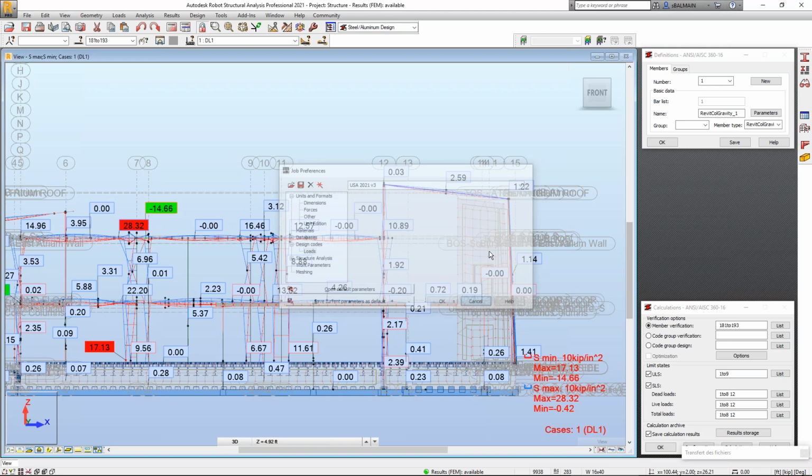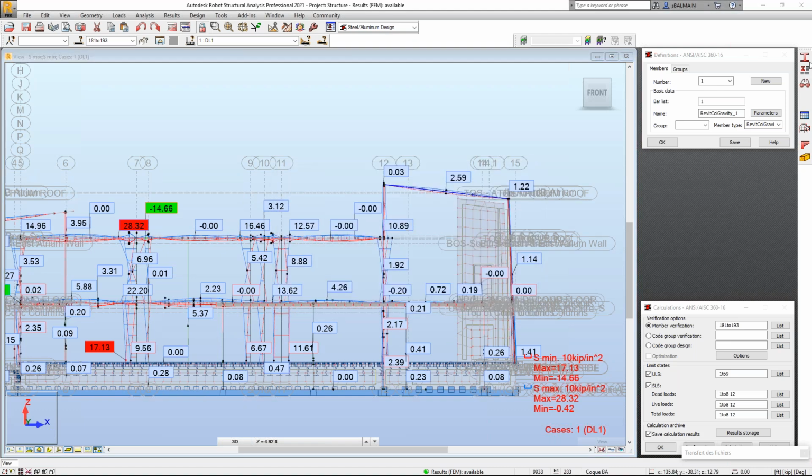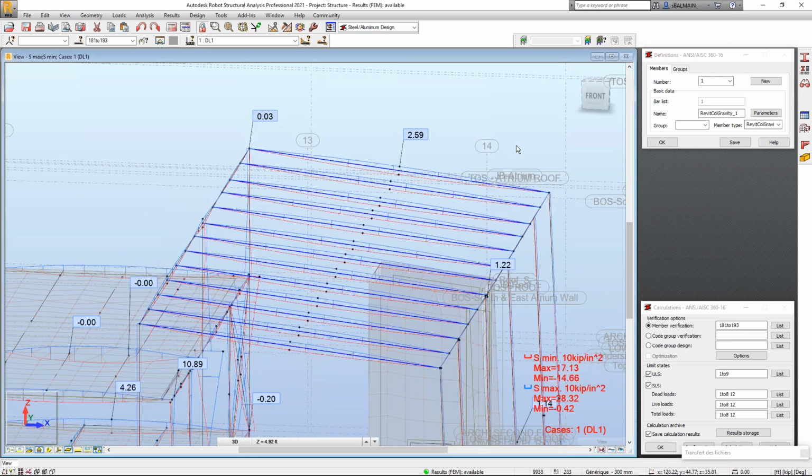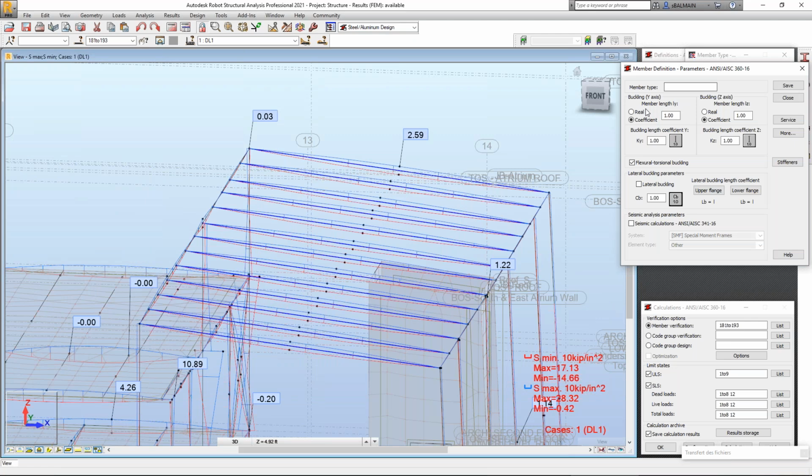Okay, so let's move. Here I will take care of this beam. So I will create a new one. I will start from a beam, and I will call it my top beam because you can change the default element. Okay. So here, for buckling, I would say we will put some small profile to avoid lateral buckling here.